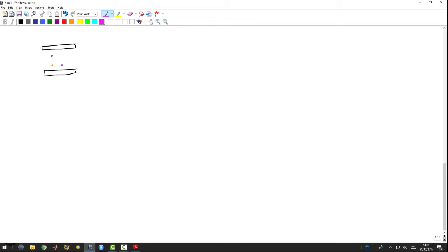So 3 points in this flow, and we have some hypothetical material fiber which is joining these points. And what happens to these material fibers when there is flow? Flow is initiated because the top plate is moving and the bottom plate is stationary. So this kind of an object placed in the flow will have higher velocities at this location and lower velocities closer to the bottom plate, because the bottom plate itself is not moving. So you can see that the blue wire will tend to rotate and become like this.